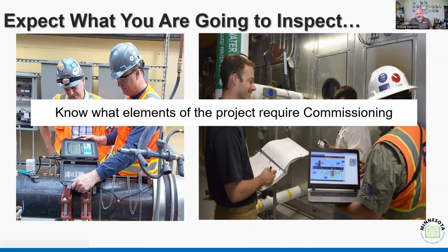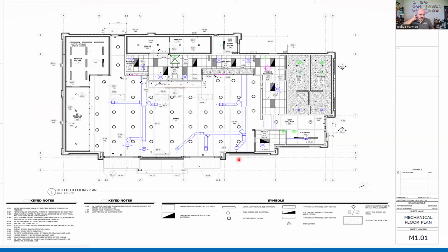Because again, the expectation is that we're going to test those systems to make sure that we have efficient buildings that operate effectively. It's not good enough to say, hey, the heat plant in the middle of the building works well, right? It turns on. After it leaves the mechanical room, we don't know what happens to it, right? And that's where, again, we have this functional testing expectation. That's why we require identification of this process up front. What test, who's doing it, when are we doing it, right? So that we know that the proper duct distribution takes place.